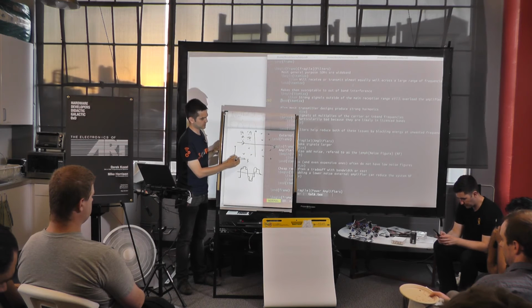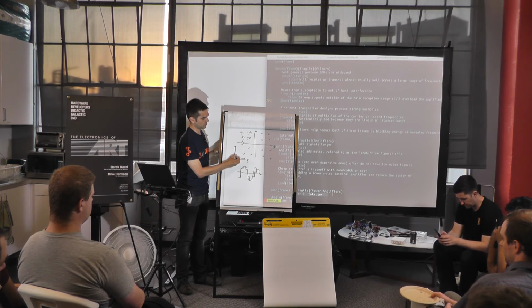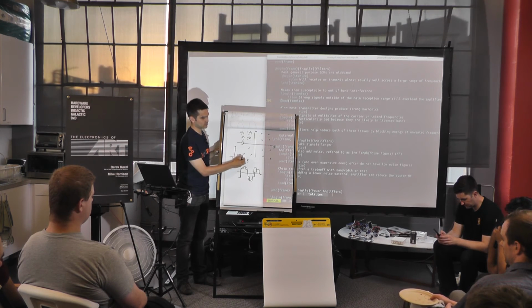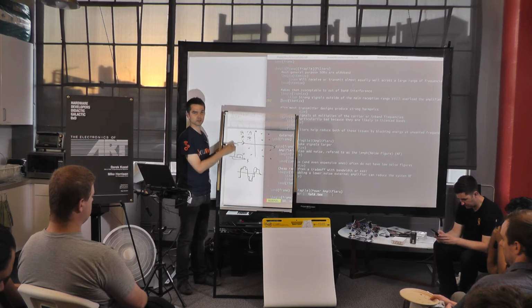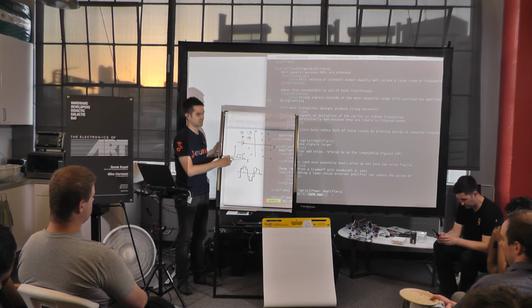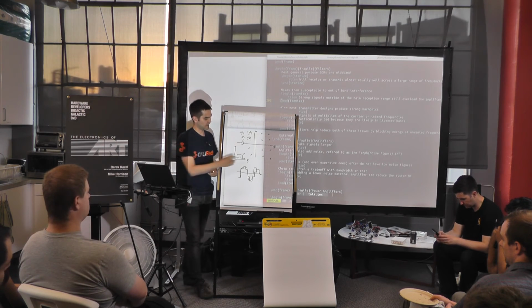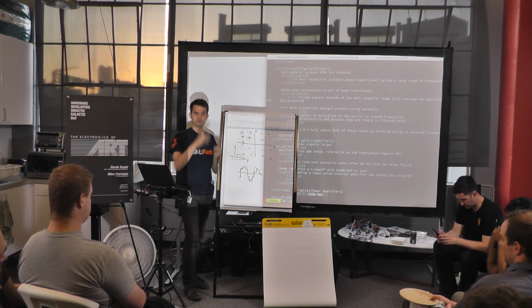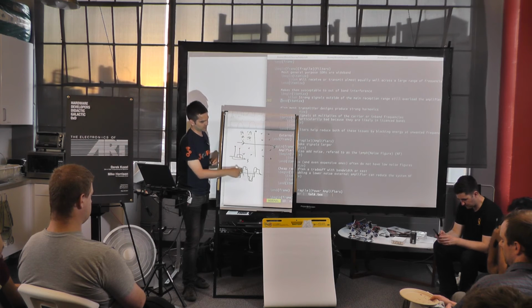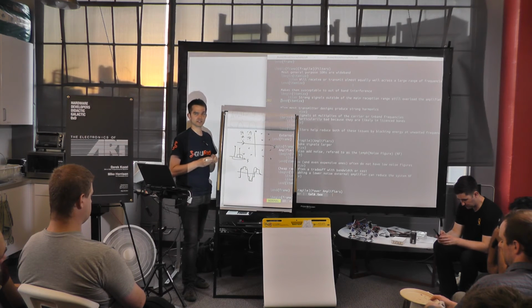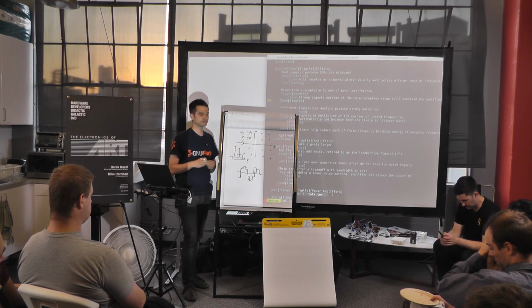If you want to see this signal and you have a filter that will only pass frequencies in this range, you can basically attenuate out. You can reduce the power of this signal, reduce the amount of energy at that frequency that actually reaches your receiver. And so then you can tune over and see it just fine, because you can increase your gain and make this into a big signal that even with your quantization noise and everything else, you can still resolve.